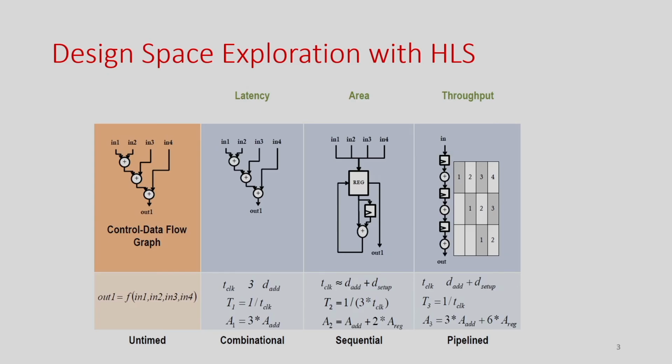And then the permutability, which is basically design space exploration. From the same specification, which is untimed, there is no objective, whether it is for power, area or timing, it is just an untimed C specification, and I can explore different kinds of designs from the same specification.